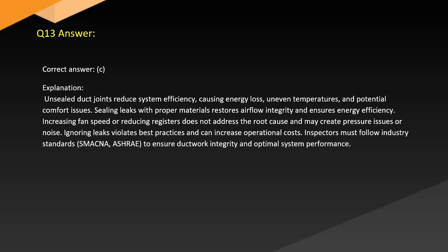Unsealed duct joints reduce system efficiency, causing energy loss, uneven temperatures, and potential comfort issues. Sealing leaks with proper materials restores airflow integrity and ensures energy efficiency. Increasing fan speed or reducing registers does not address the root cause and may create pressure issues or noise. Ignoring leaks violates best practices and can increase operational costs. Inspectors must follow industry standards, SMACNA and ASHRAE, to ensure ductwork integrity and optimal system performance.